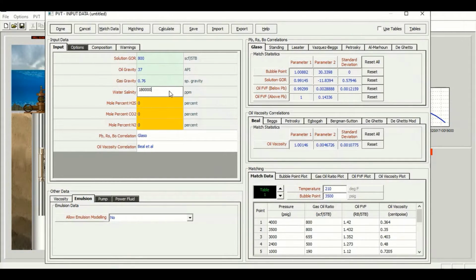If you inject diluent to make the salinity lower, to make the fluid more dilute, you inject water. But of course, if you inject water, then your flow rate will decrease because now the fluid will be heavier, and the well will work harder to push the flow.